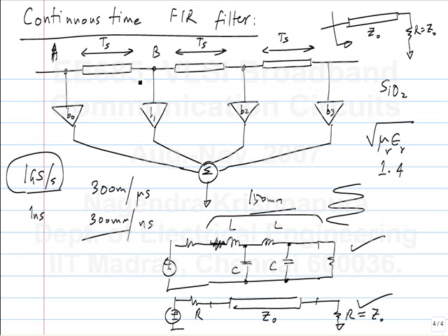This may not be a big problem. Many times you operate over a very narrow range, but if you do operate over a wide range of data rates and you need equalization, this may be hard to implement compared to digital, or at least a delay line type of implementation where the amount of delay is determined by some clock edge. So by changing the clock frequency, everything scales.